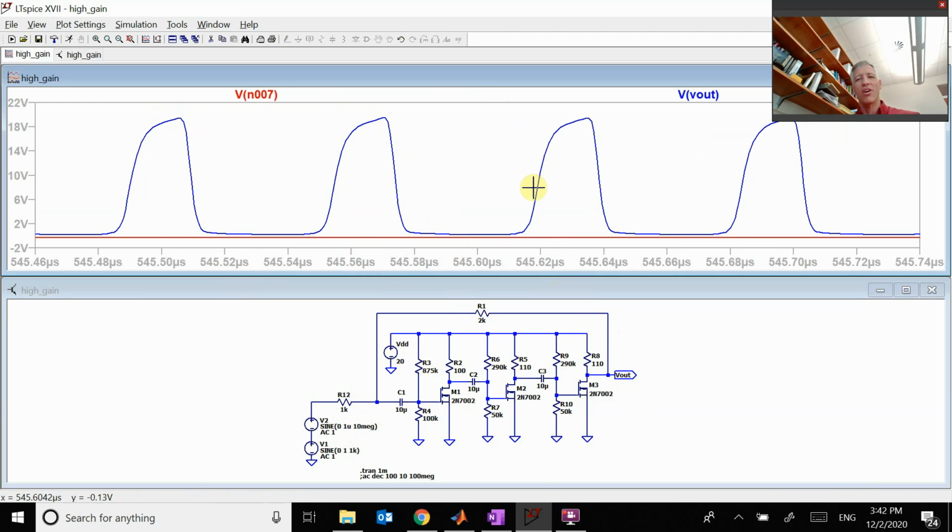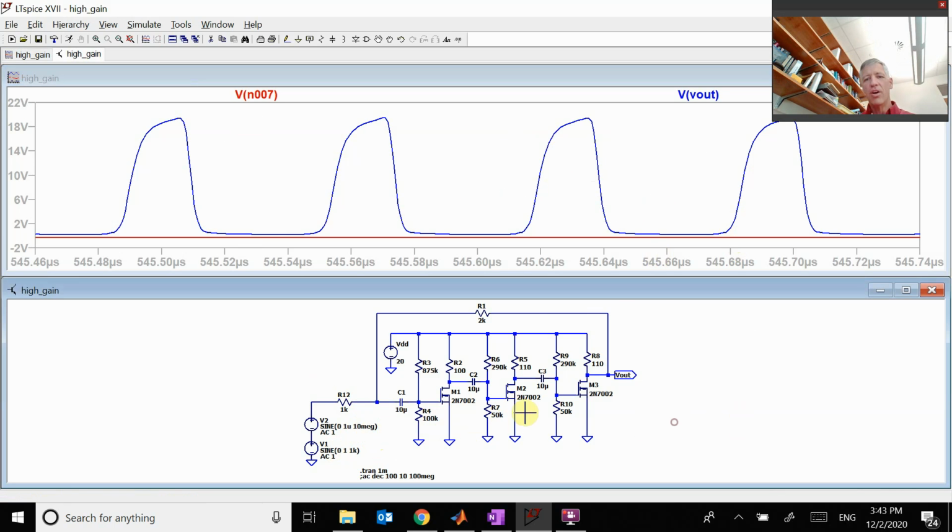And so this is called oscillation or ringing of a circuit. And all I had to do was pick up a tiny amount of noise that could be picked up from the air with radio signals or just some random noise by temperature fluctuations in resistors. And so we need to make sure that this is stable. So this is because my gain margin was all messed up.